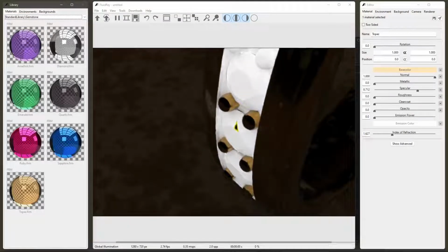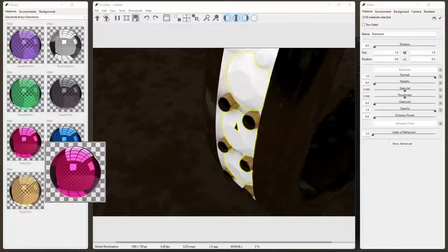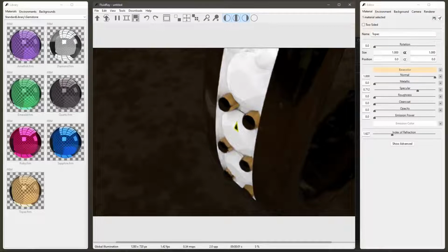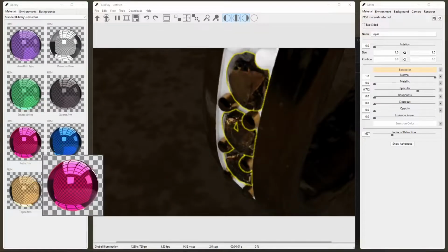You can see that it only applied on a single triangle. So it's going to take an infinite time if I don't just shift click and then select all by material, and then apply the material to the whole selection. I'm going to show you again. This is really important, because even though this is a small object, it contains a lot of details. So shift click, select all by the same material, and fortunately by importing with Rhino, it detects the differences of material. Then right click on the material and assign to the whole selection.